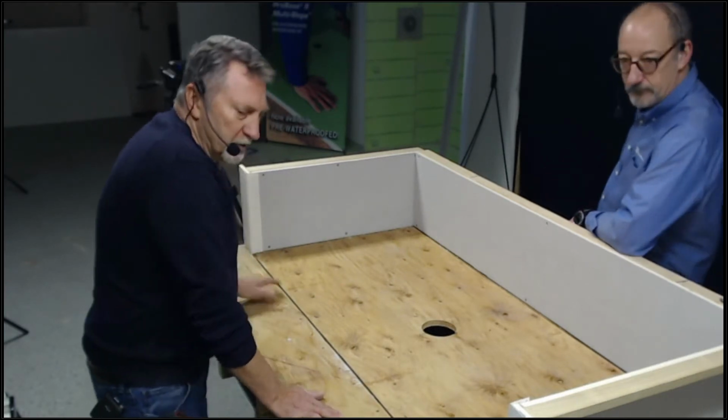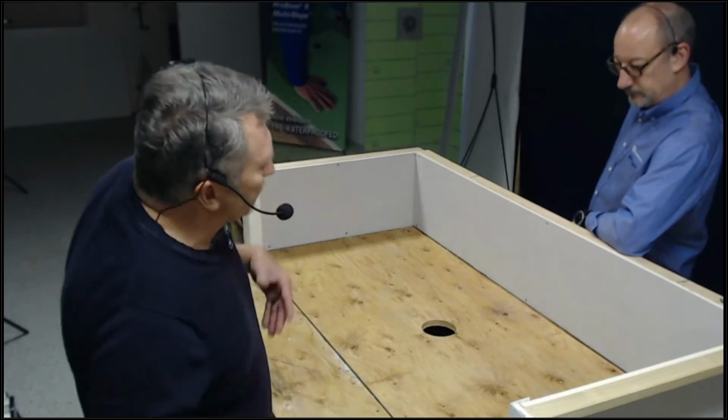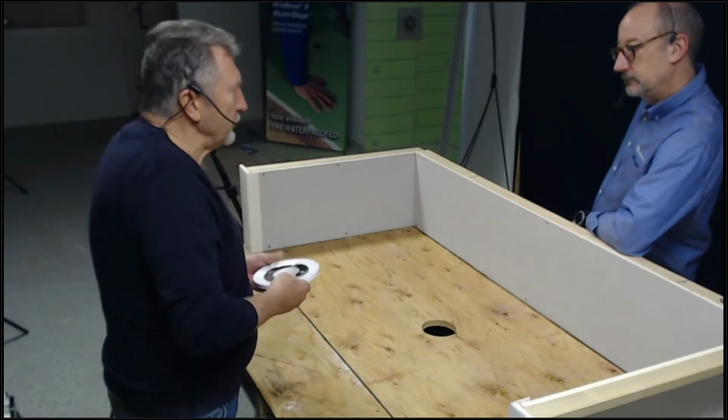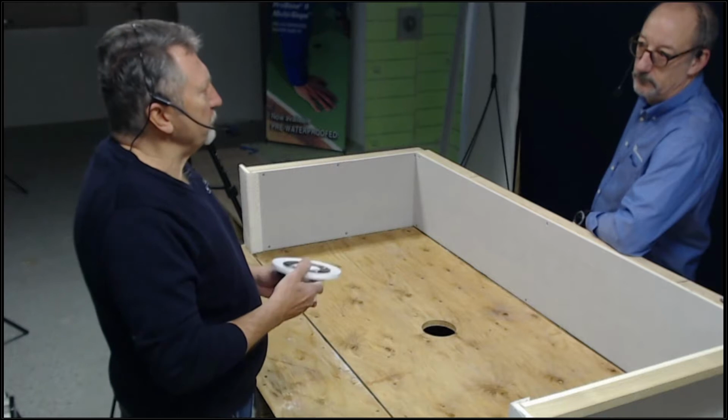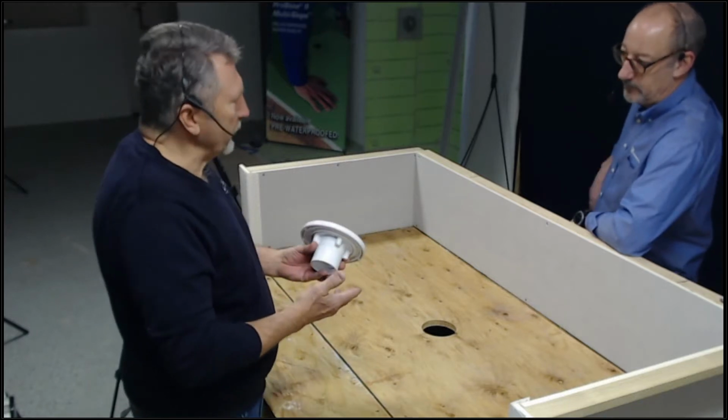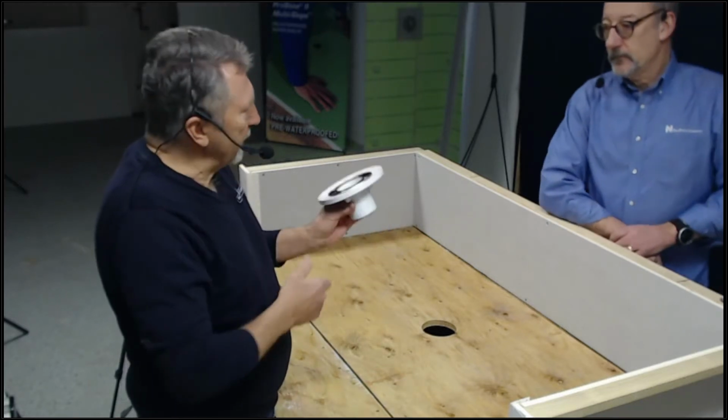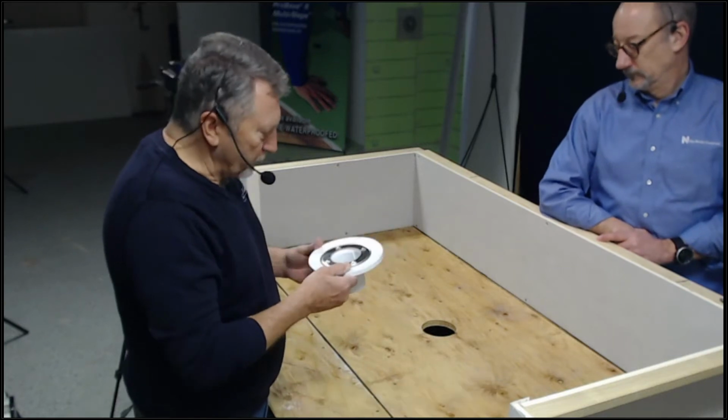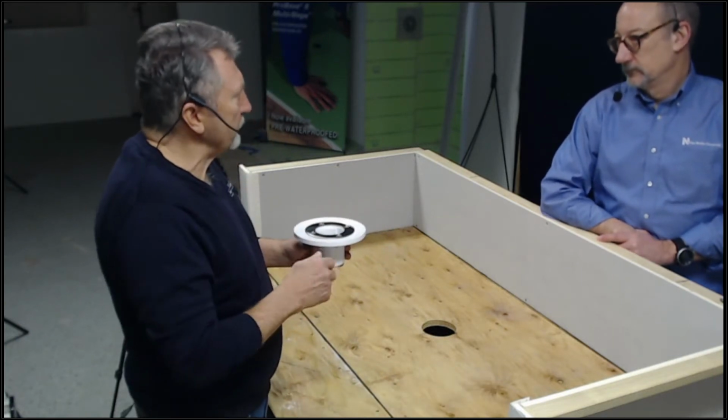So first of all, we're going to install the drain. Today we're going to be using our Noble Freestyle thin bed drain. One of your newer drains. Yeah, one of our newer drains. As you can see, the drain is only a 1/2 inch profile. So you just go directly to substrate and you'll start at a 1/2 inch and then slope from there.